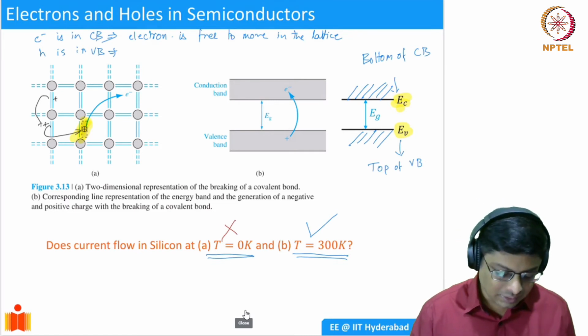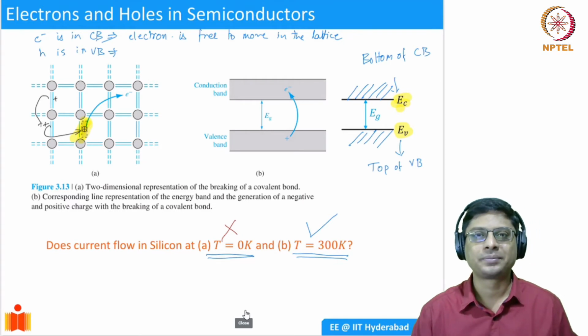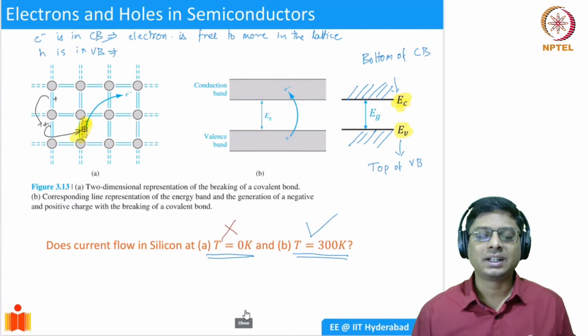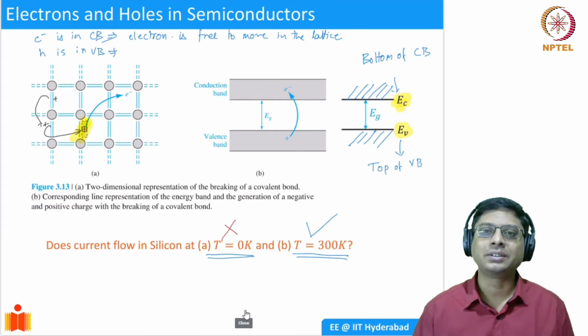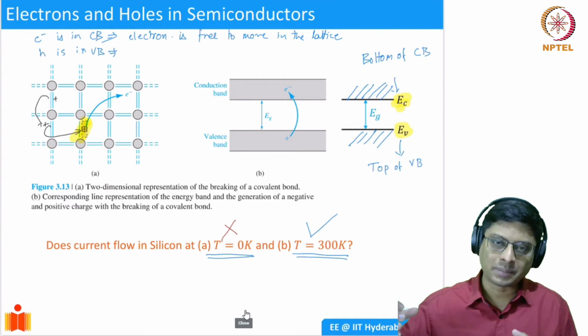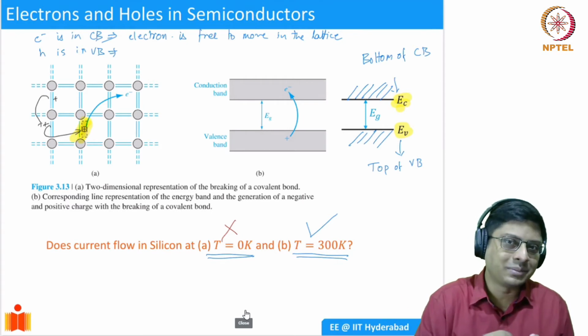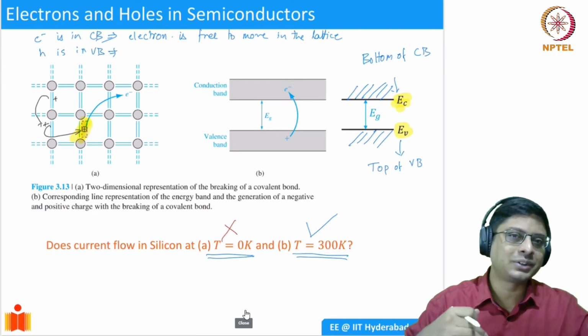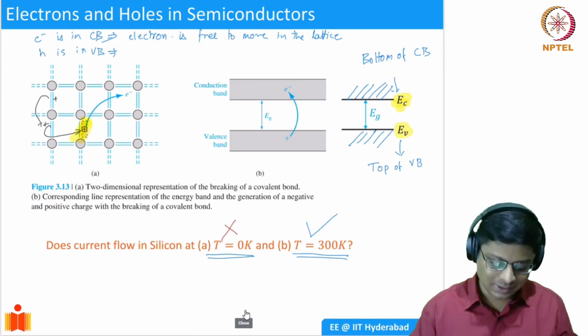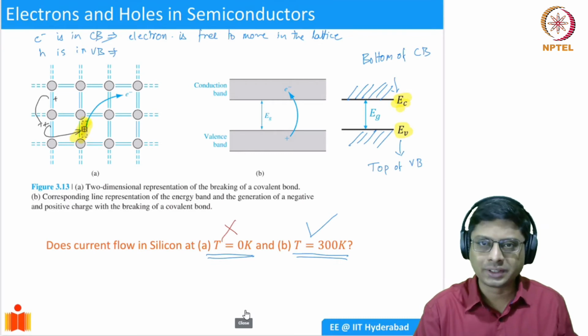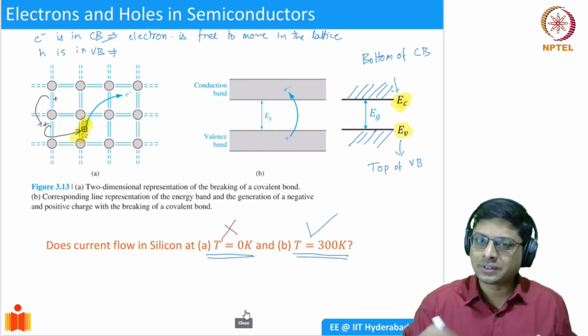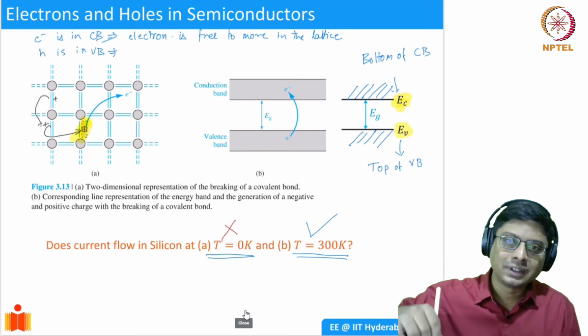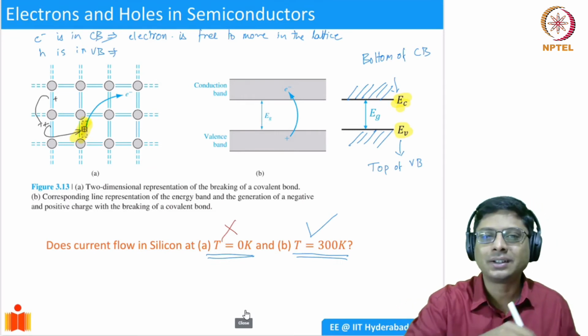Okay. So now you are able to move this. The hole is actually able to move through the lattice. It is something similar to what happens if you have a bubble of air in water. What happens? The bubble moves. It's not actually the bubble moving, but it is the water which is moving, right? The background, the water, is moving, and because of that, the bubble appears to move. Similarly, when we say the motion of a hole, it is in fact electrons which are moving, but it appears as if the vacant state is moving. Okay, so please remember this.